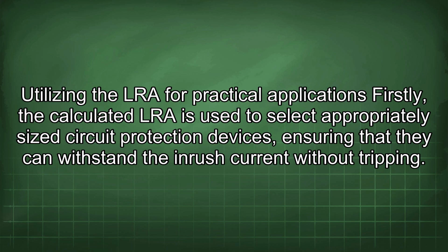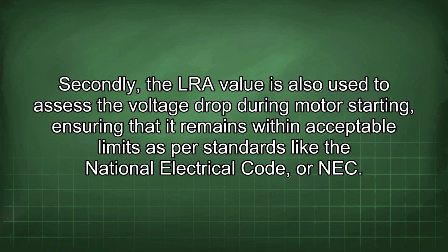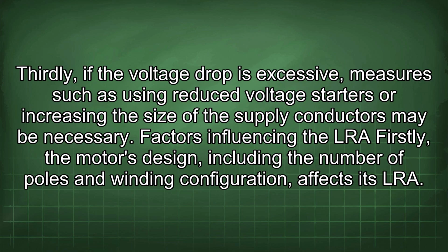Utilizing the LRA for practical applications. Firstly, the calculated LRA is used to select appropriately sized circuit protection devices, ensuring that they can withstand the inrush current without tripping. Secondly, the LRA value is also used to assess the voltage drop during motor starting, ensuring that it remains within acceptable limits as per standards like the National Electrical Code, or NEC. Thirdly, if the voltage drop is excessive, measures such as using reduced voltage starters or increasing the size of the supply conductors may be necessary.